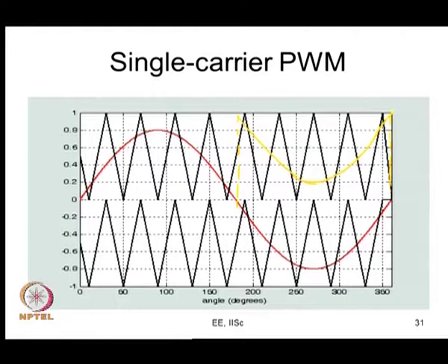So, this orange one is the negative R phase shifted. I have the same waveform here for the positive half cycle, and for the negative half cycle let me phase shift like this. So, what do I have here? What is the difference between this and that? This is same as MR. In the negative half cycle, this is equal to 1 plus MR, that is what has been done. Now, you compare. The comparison between this and the triangle is same as the comparison between this and triangle, there is actually no difference really at all.